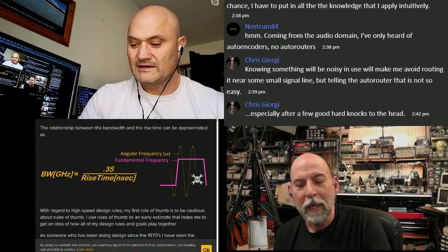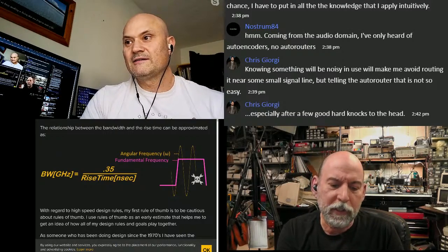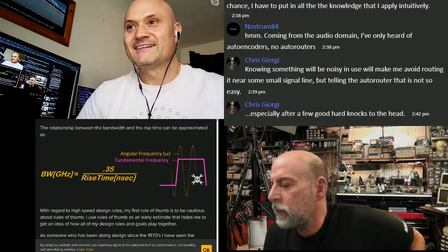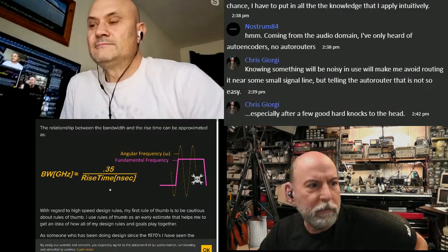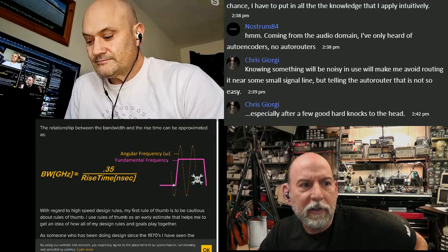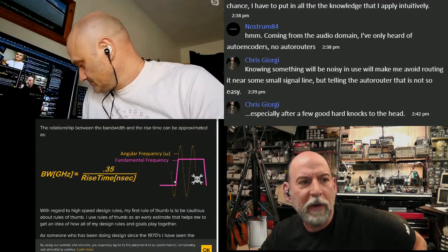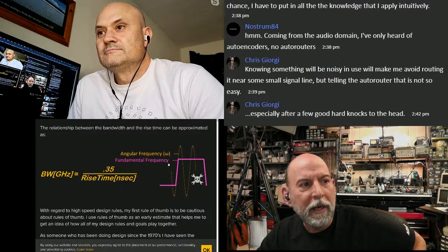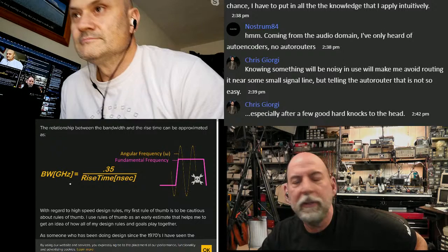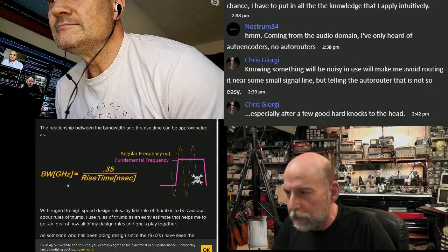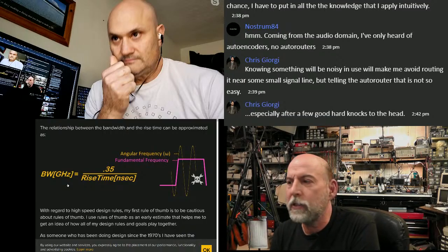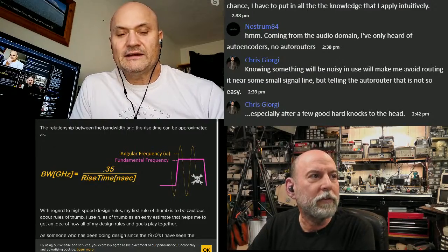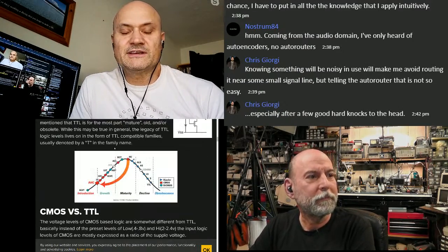Yeah. So, hey, you mentioned the ACT parts getting faster, so I brought up this little guy again. This is the real answer to when ACT parts get faster, and radiation we're talking about: this rising edge gets faster too. So the part not only propagates faster, it does a faster slew rate, faster rise and fall time. And that means the angular frequency, the bandwidth that comes out of it, is higher. Not way higher, but higher. So that's what a faster part does, it makes a faster edge in addition to a faster latency. Yeah, and that's why you run into EMI problems.